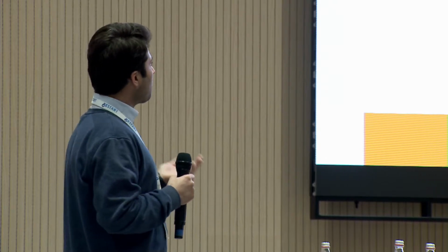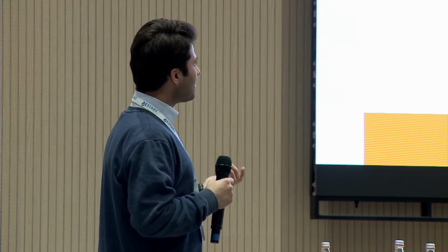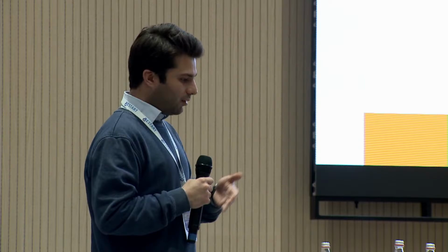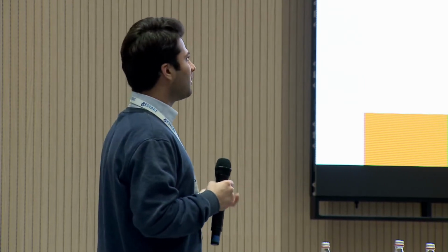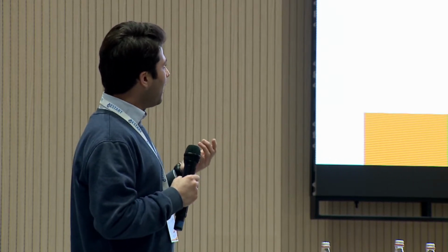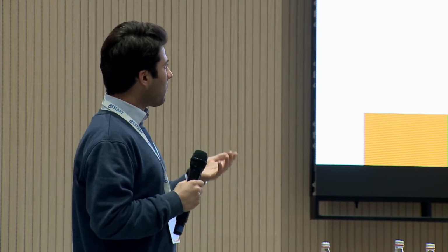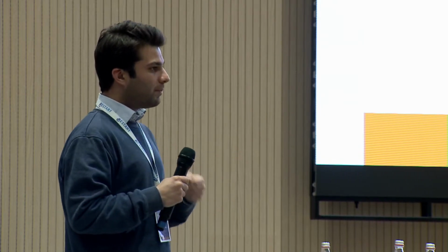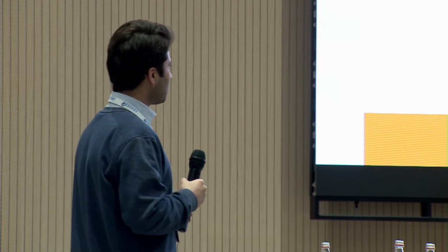So you can have this kind of device at 1/5 or 1/3 of the cost of expensive monitoring devices. The third thing is biofouling that we are still thinking about, because there is no way to escape it: the plants will grow around the sensors, and at the end we can just slow down the growth rate, but we still have this problem. And we need to make the device completely waterproof, because we are working in a really harsh environment, and we need to think about how it can survive different kinds of tides and different heights of waves, because they can completely break the device when there are tides at night. So it's really important to study more about this problem.